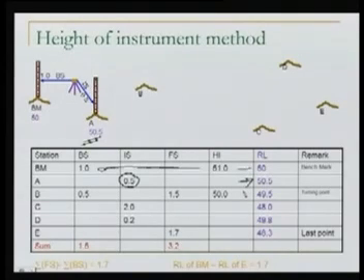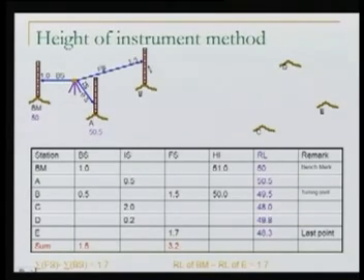Well, next our job is to determine the RLs of other points. We shift our staff to B. Let us do it. The staff goes to B, and after shifting it, again we will take a sight at B. Now this sight I am calling a foresight. In a moment we'll understand why this was a foresight and why the earlier one was an intermediate sight.